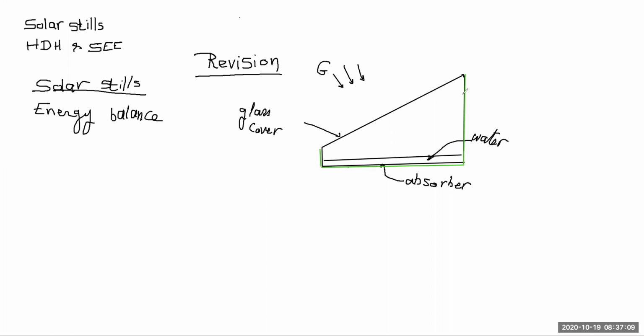Either the solar still itself is made of insulating material like wood or fiberglass, and then you put inside it a layer of metallic black painted surface acting as an absorber, or sometimes people make the whole solar still from a metallic part and put all of it inside a wooden box.